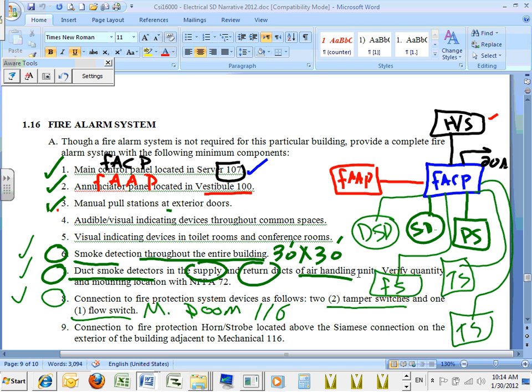You're going to use the fire alarm control panel processor, and it will be programmed to give you outputs, to give you activation. Annunciating devices. You need annunciating devices. Okay, the first annunciating device is the horn strobe. What's a horn strobe? You're looking at it right there. So when I have a fire in any area, it will go to the fire alarm control panel. The fire alarm control panel will send a 24-volt signal to these guys to activate them. And I'm sure a few of you have seen these activated, very loud and very bright. It's supposed to get you out of there because there's a fire in the building. Cool? We've seen it before.